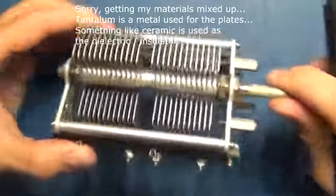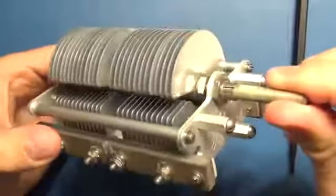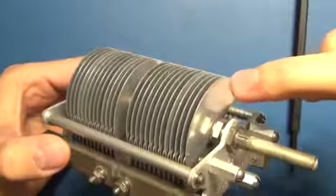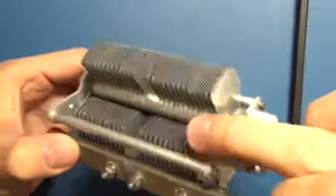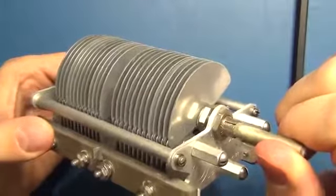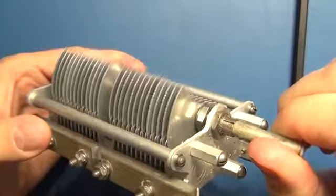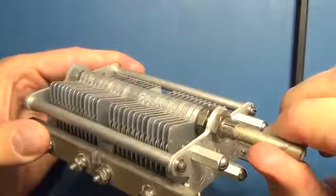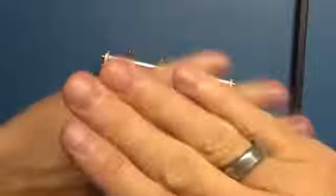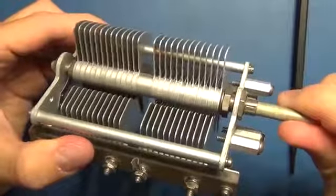Now on this capacitor, which is a variable capacitor, you can see that the overlap of the plates changes. As I turn this round, this will be one side of the capacitor, and this will be the other side, these plates over here. And as I put them together, the surface area that starts intersecting and crossing is going to increase. So in this case, the capacitance is actually going to increase as the plates are folded into each other, because you've got more cross-sectional area across from each other. And then obviously that is reduced as this comes up.